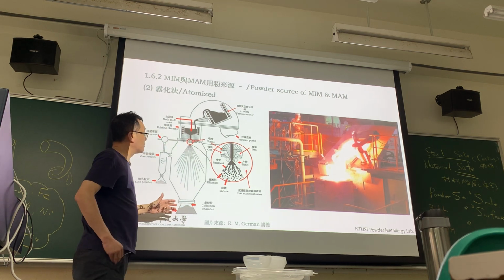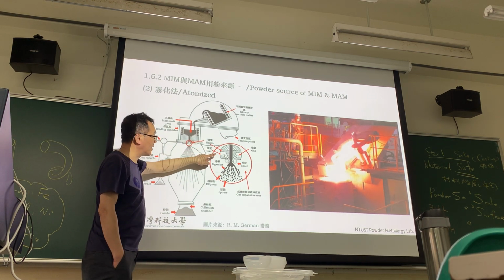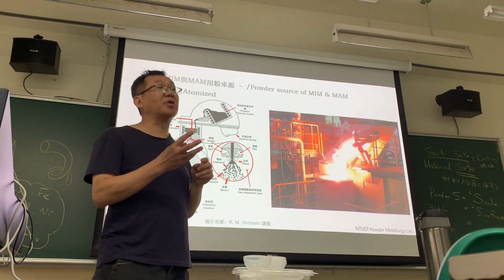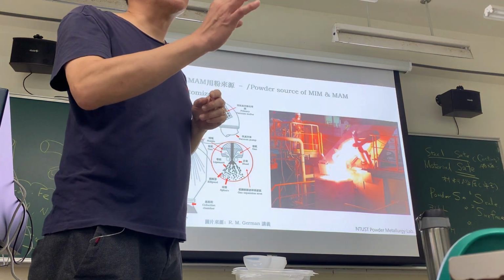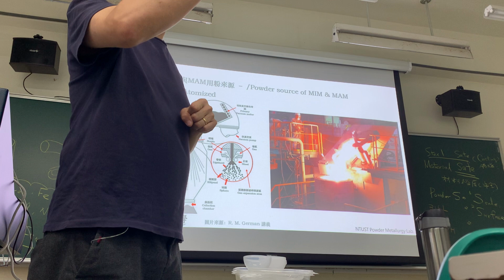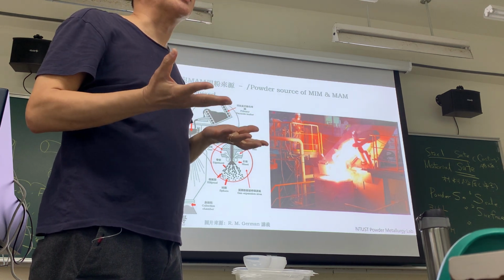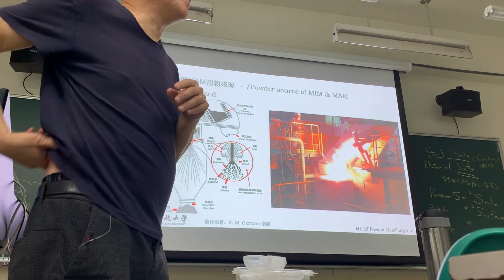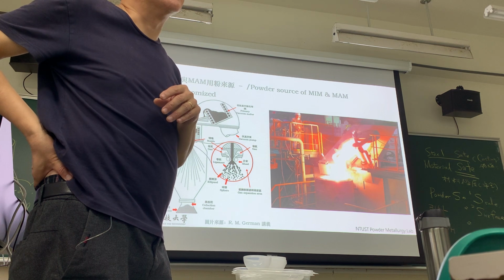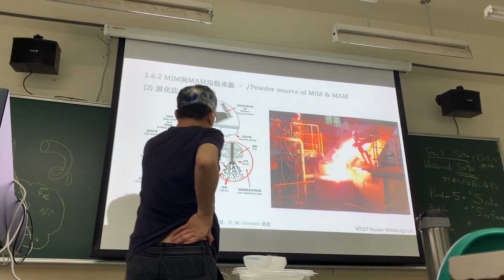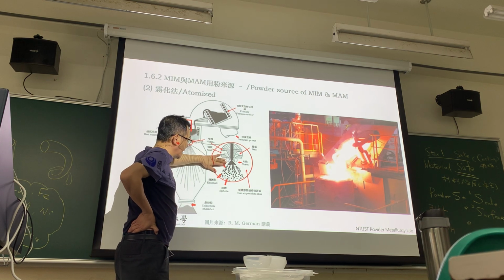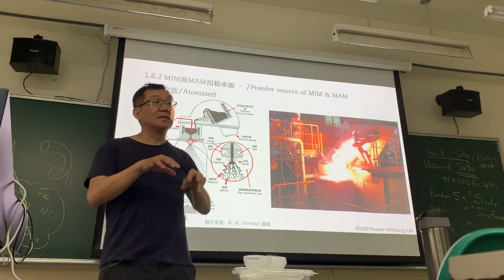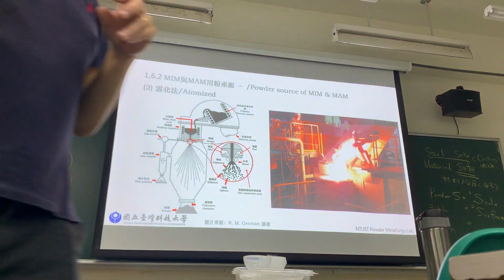Okay. So sometimes we use gas. If we use gas that is slower, with low pressure, the powder will become like a ball, very good. But the speed is not good. Why? Because every minute is just about 10 gram, 15 gram. So we exchange the cooling gas. Maybe here we enter high pressure water. So use the high pressure water.